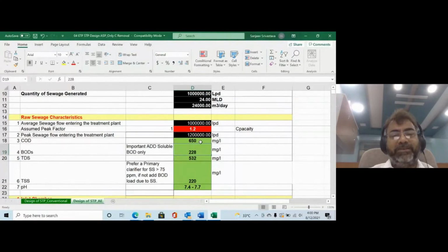One you test as it is. The second, you pass it through 0.45 micron paper. That 0.45 micron paper is the same paper which is used for measurement of silt density index for RO. So if you use that quality of paper, whatever permeate or product is coming out from there, you take and send it to the laboratory for testing.